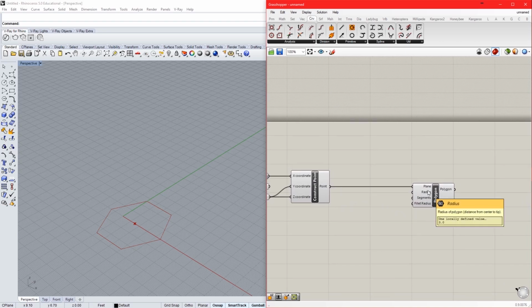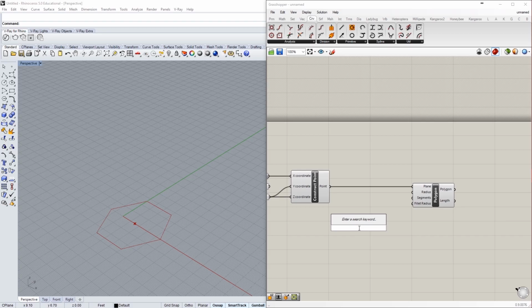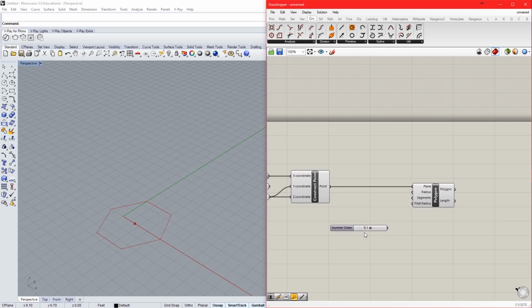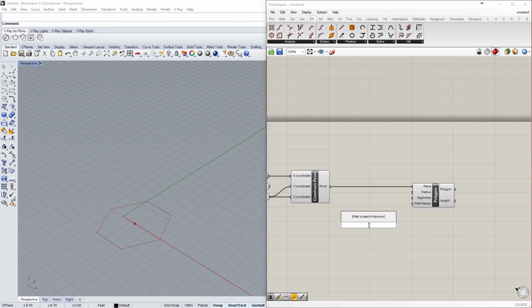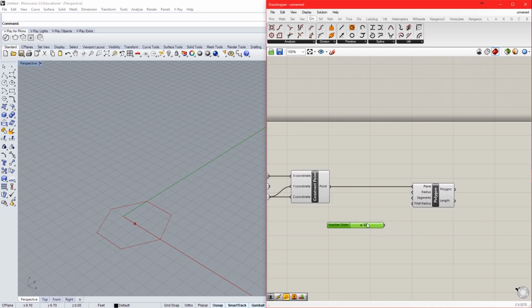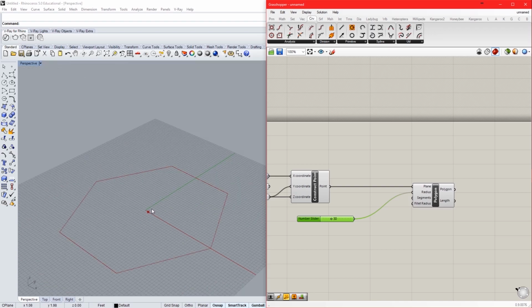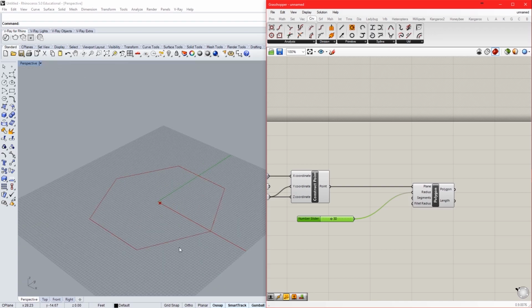So then I define a radius, and I see that the radius right now is set to 3.0. So yeah, I'll work between 0 and 10, and I'll work with 1 decimal point. So I'll type in 5.1. And now I have a properly scaled number slider. Although if we're working in feet, let's just say if we're working for real, what's good for like, I'm just going to go with 60 feet. So the radius would be 30. Right? So that would make one floor. That's 30 feet in radius, so 60 feet across.